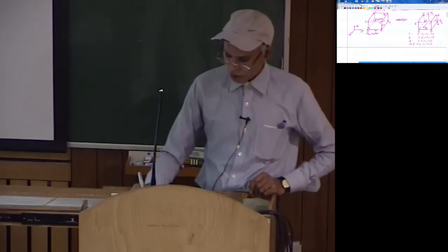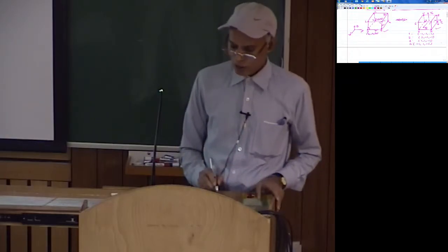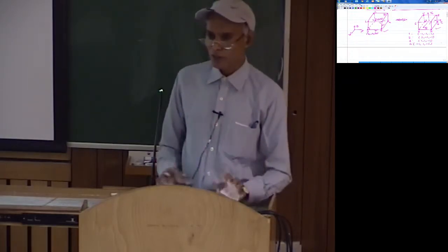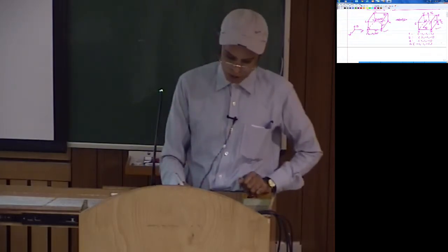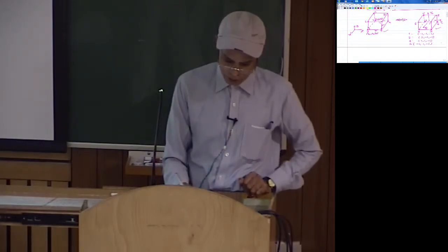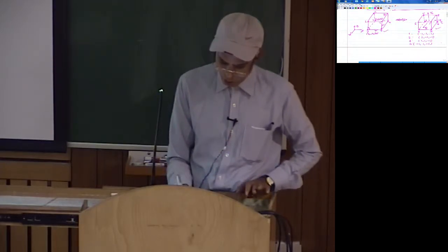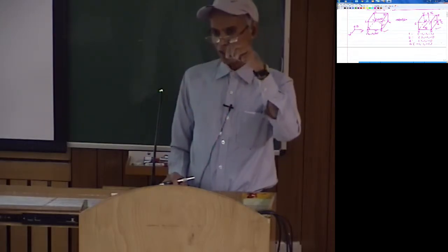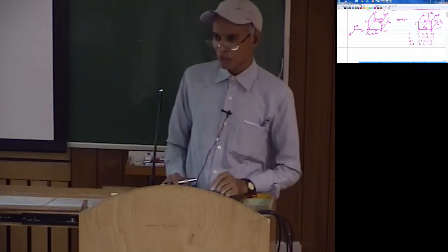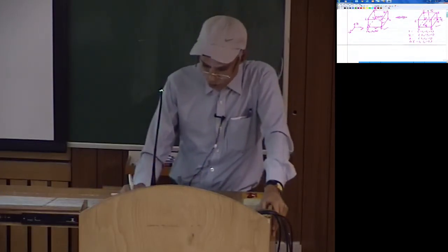So this is the element in the natural coordinate space. This is the element in the physical coordinate space. And I already mentioned to you that this can be reduced to a tetrahedron by appropriately collapsing the nodes. If we make all of 5, 6, 7 and 8 as one node, and similarly any one of these, 1 or 4 or 3 and 4, the base will be a triangle, and then one point on top joined to the vertices of the base triangle, you get a tetrahedron with 4 faces. So it can be deduced from this.